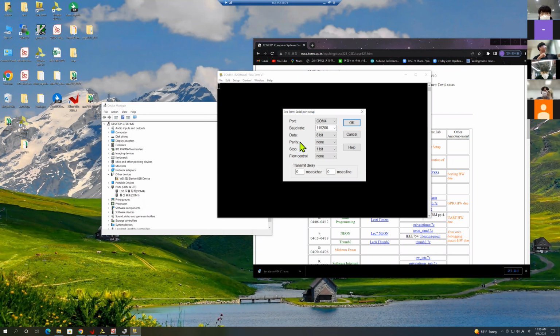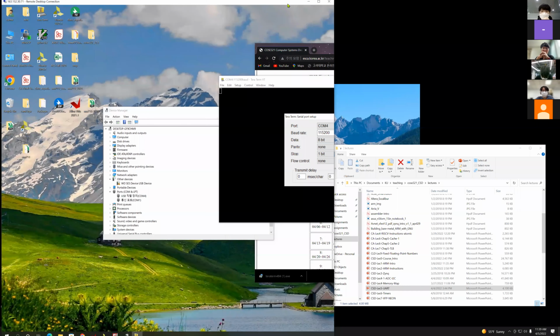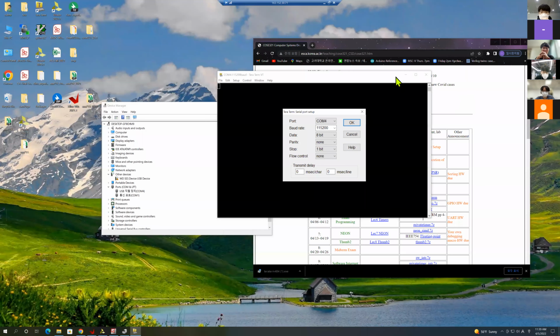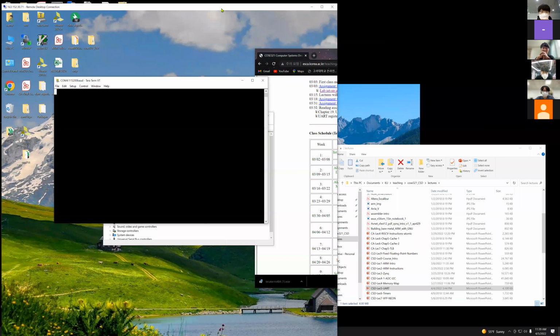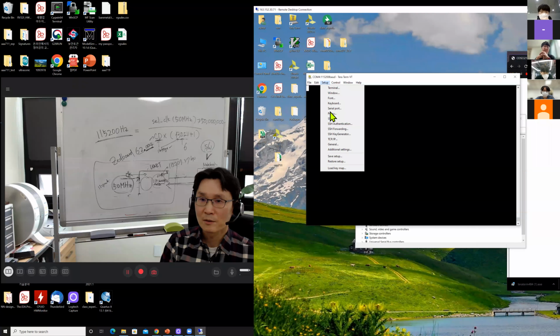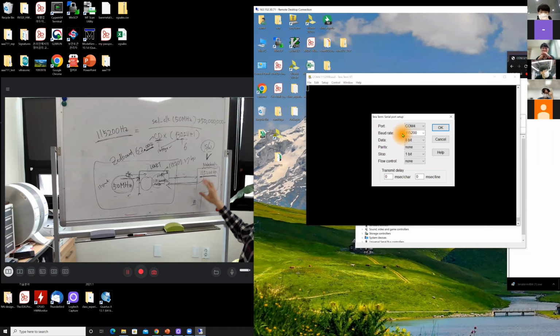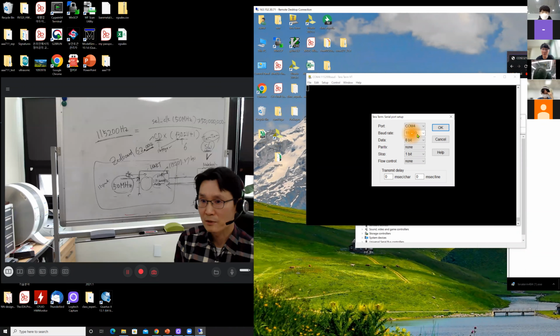And look at this, the baud rate speed. I want to set the speed to 115200, on the PC side. Set up the serial port, then that is the speed. On the PC side, you are setting the speed and packet format, using that software, Teraterm. Before normal operation, you set the speed and packet format. What is the speed? 115200 bits per second.